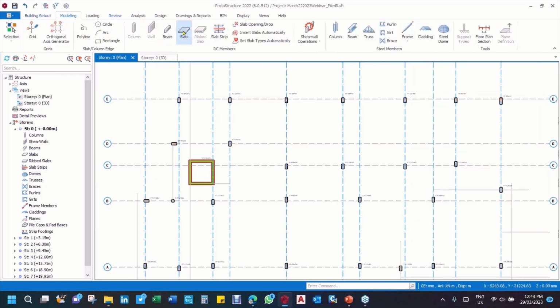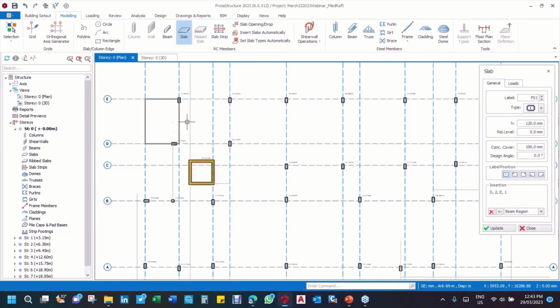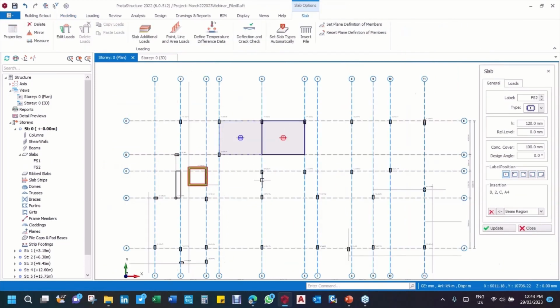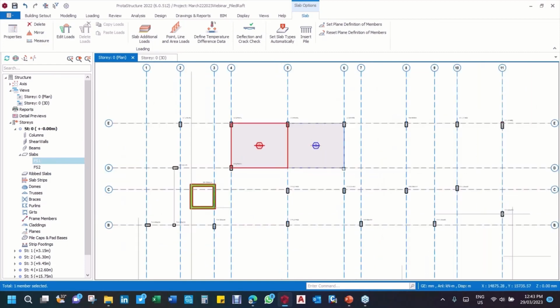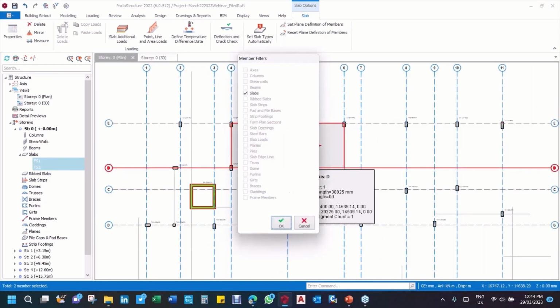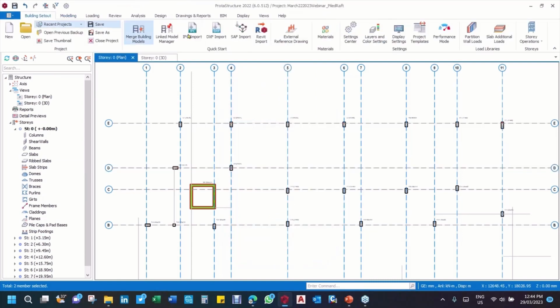For instance, we can model this slab and then come here to insert all the slab here. We can come here, insert, and then we are good. But that is not the approach I want us to use today. But you can also do this. It is permitted. So what we are going to use today, which I normally use and which I encourage you, is to use external referencing.